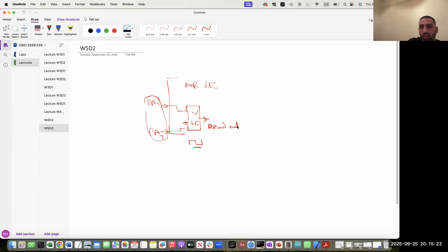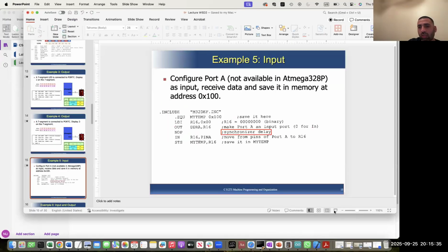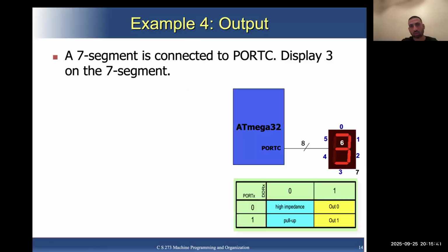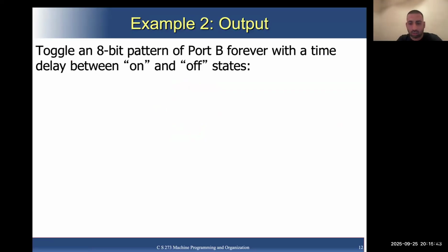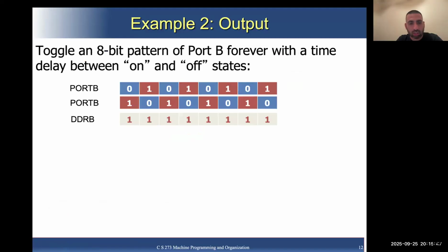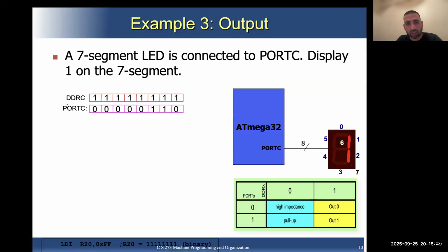Because you are not waiting for one clock cycle, that's why we are putting a nop in between, so that one clock cycle passes, which means that whatever the input is, it then becomes available on the output of the internal latching circuitry.